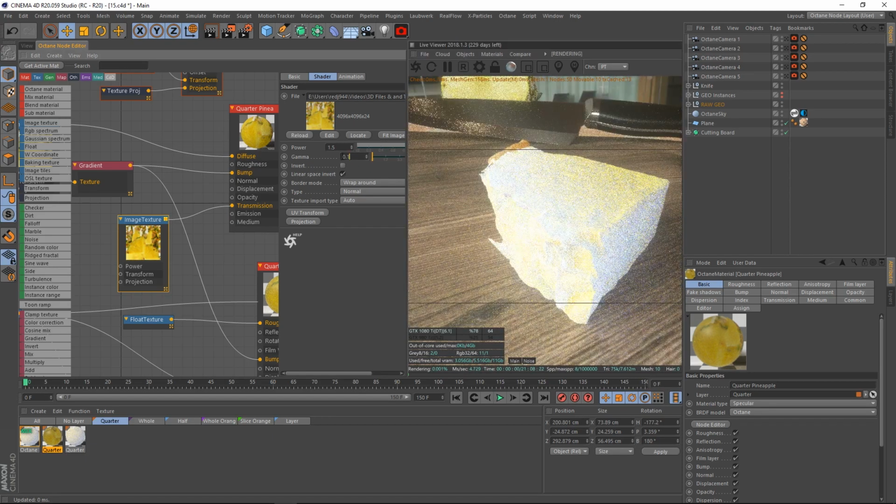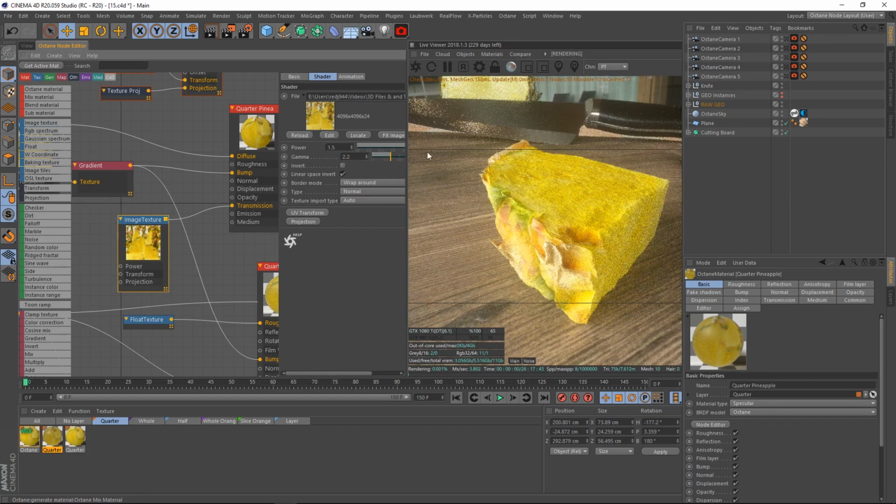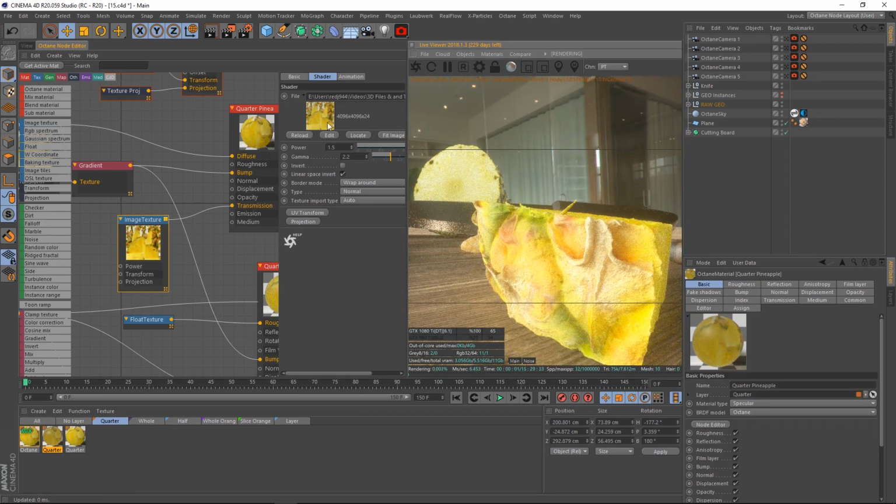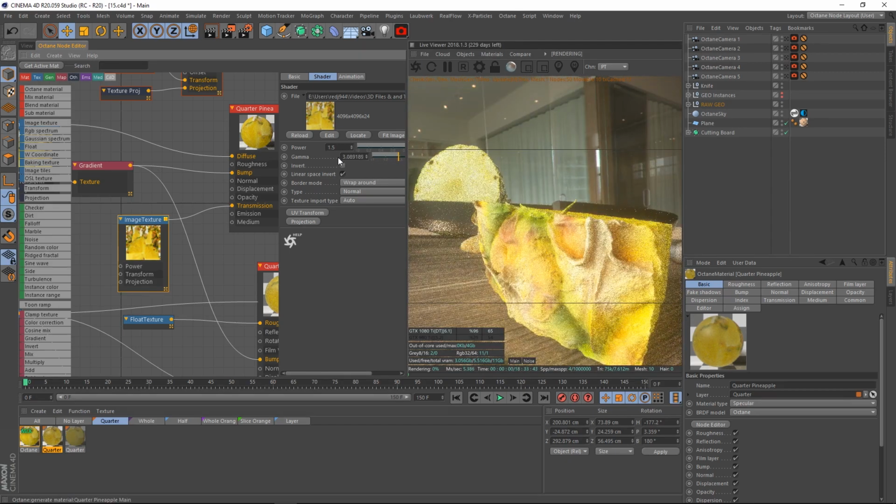You can see what we're doing here. If I had a gamma 2.2, it has too many white spots, too many hot spots. What I want to do is just kind of even the overall brightness of it out. So I just kind of darkened everything down with a gamma value of 3, and then I punched the value of everything up more to 1.5, just so we can have a more even kind of brightness of it coming through.